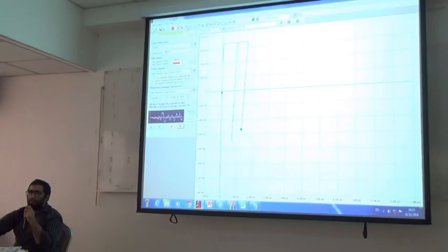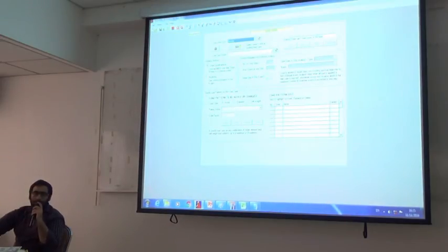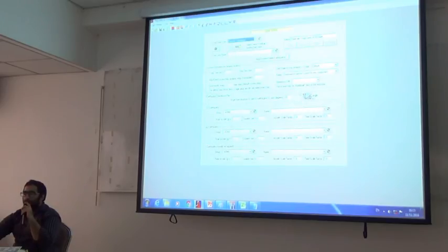One more thing that we should mention right now is that sometimes when you want to plot the residual drift, you have to increase the time of the analysis. So, for example, if you have a ground motion, I'm selecting the central ground motion over here, you can see that the duration of the ground motion mentioned in this tab is 25 seconds. So what you do is you just increase the time of the analysis.